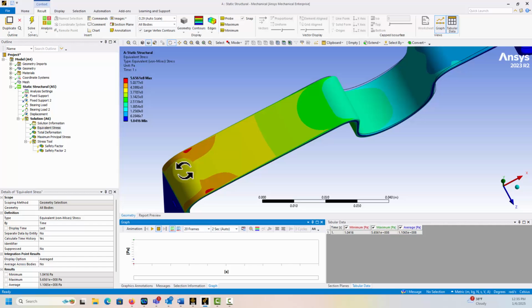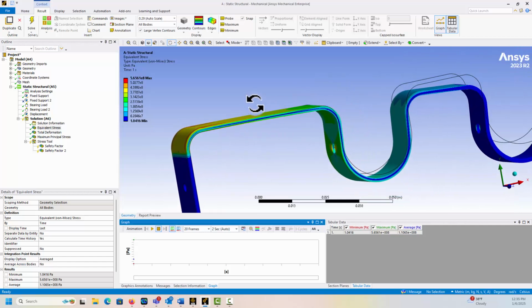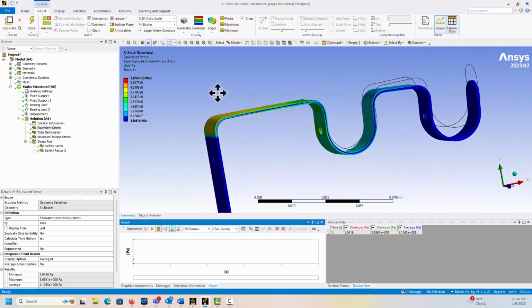It kind of helps tell me I don't have things well resolved because of how they smooth it out. So I like to see that rather than going to the smooth contours, which can hide some things I may want to see. So I like to do the contour bands. I like the undeformed as a reference. Okay, so that's one factor.